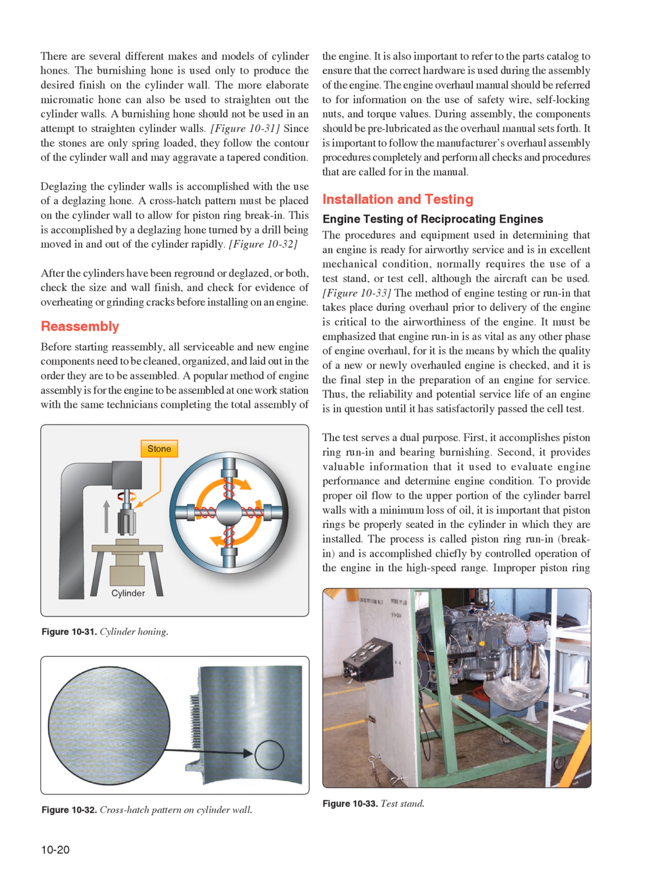It must be emphasized that engine run-in is as vital as any other phase of engine overhaul, for it is the means by which the quality of a new or newly overhauled engine is checked, and it is the final step in the preparation of an engine for service. Thus, the reliability and potential service life of an engine is in question until it has satisfactorily passed the cell test. The test serves a dual purpose. First, it accomplishes piston ring run-in and bearing burnishing. Second, it provides valuable information that is used to evaluate engine performance and determine engine condition.